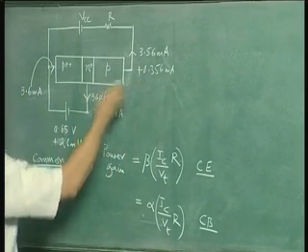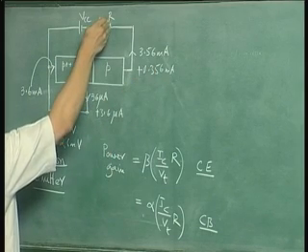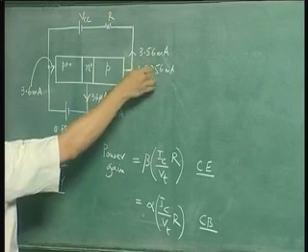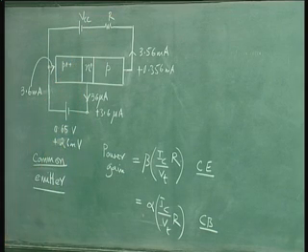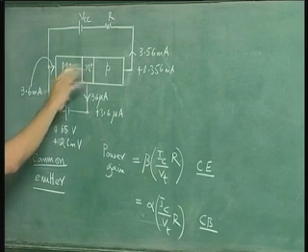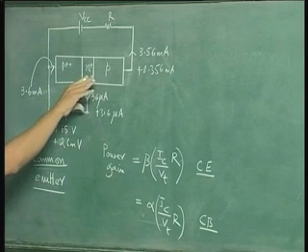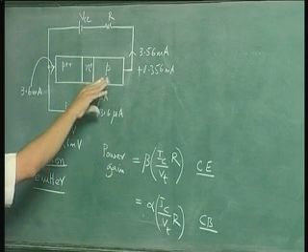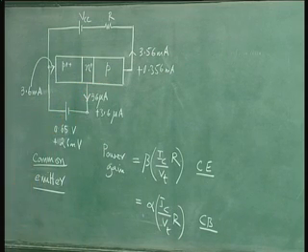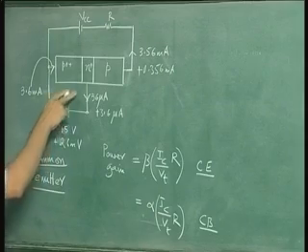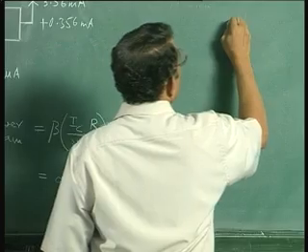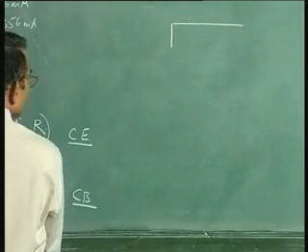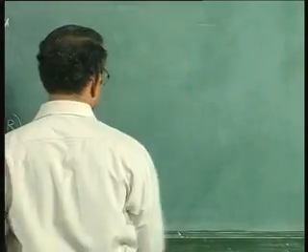In addition, anyway you have voltage gain, because when you pass this through the resistance R, if it is 1 kilo ohm, then 0.356 milliamps into 1 kilo ohm is the output voltage change in response to this input voltage change. Now let us build up from here the normal common emitter amplifier circuit that we see with many more resistors than this. That can be built up very easily from here as follows. So we will draw the same circuit using the symbol of the transistor first.